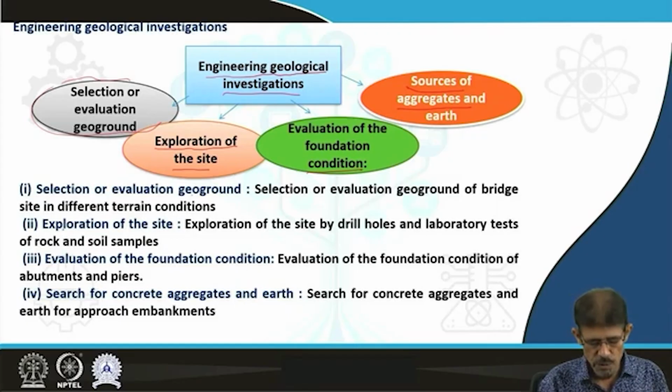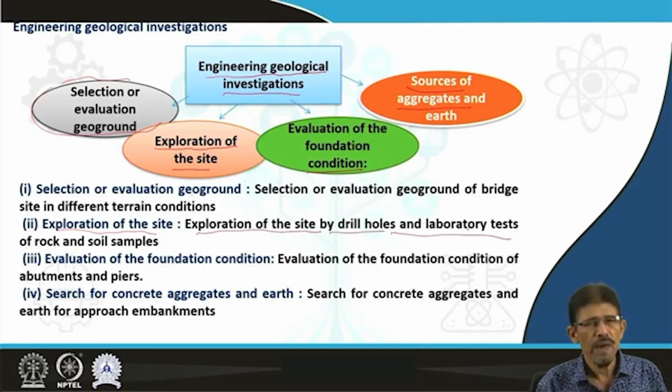Second, exploration of the site by drill holes and collection of samples, then laboratory testing of the collected samples to see the response of strata or soil layers with respect to the expected imposed load due to the superstructure of the bridge and the dead and live load of traffic for a traffic bridge.